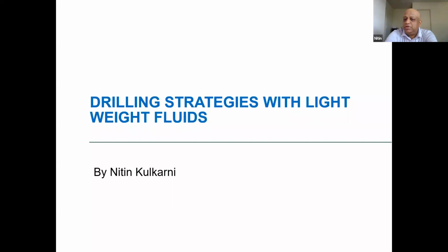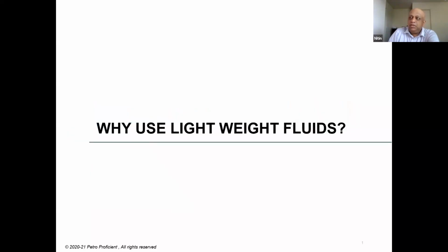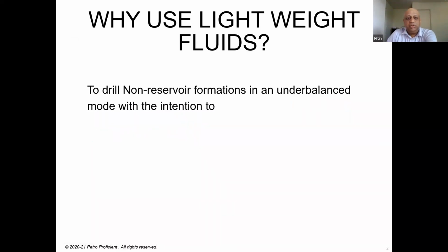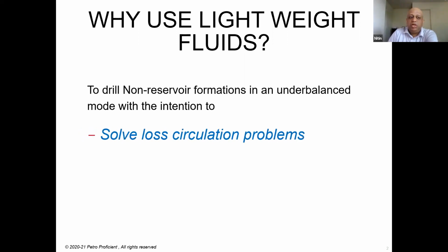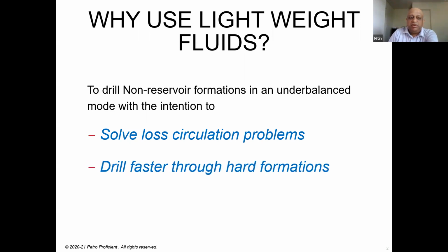This basically deals with the use of air foam aerated drilling, aerated mud system, and how we can use lightweight fluid. So let's get started with the presentation. So why use lightweight fluid? This is a question that we are trying to answer here today. The objective is to drill non-reservoir formations in underbalanced mode with the intention to solve loss circulation problems and drill faster through hard rock formations.